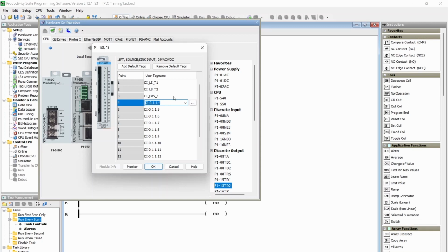Okay, now we're going to do the valve position switch. Now you notice I left the DIs in here. I did that for a reason. Let's go ahead and do the valve. We're going to call this valve 1 because we may add more later, underscore, and we're going to say open.